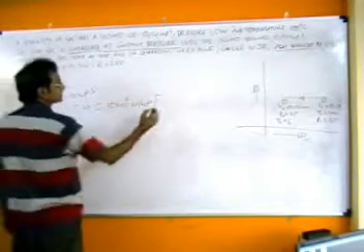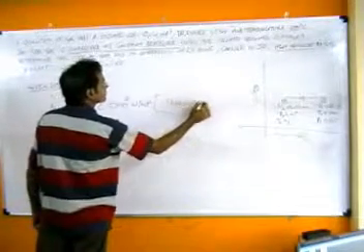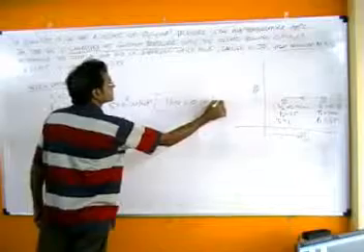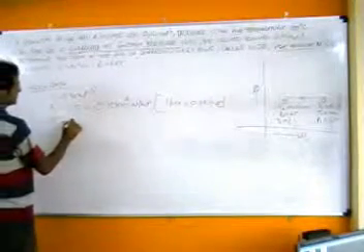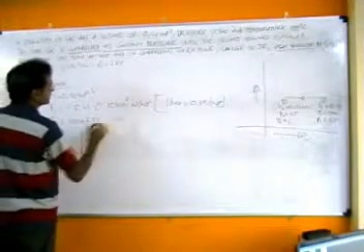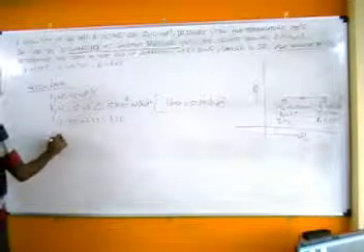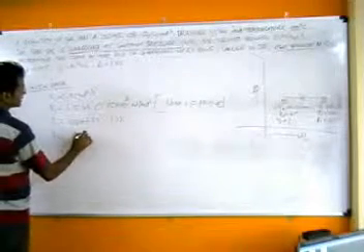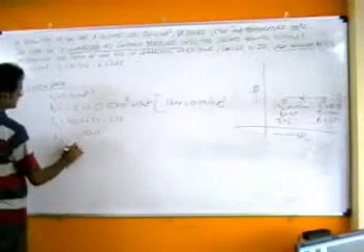You must remember that 1 bar equals 10 to the power of 5 Newton per meter square, and then temperature, which is 100 degrees centigrade, should get converted to Kelvin immediately while taking down the data, and the value of P2 remains the same as 0.15 into 10 to the power of 6, and the temperature is what is asked.